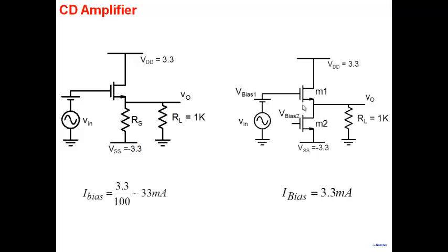But a major limitation of this particular stage was we saw that if you run it at plus 3 and minus 3 here, then what happens is the output swing is compromised here. The output voltage here is one VGS drop less than whatever is the voltage here. And if this input is also coming from a circuit which is plus 3.3 and minus 3.3 here, so this can only go as high as plus 3.3. And so the voltage here, positive swing, will be limited by at least a VGS drop here. So that was the limitation of common drain stage here, right?